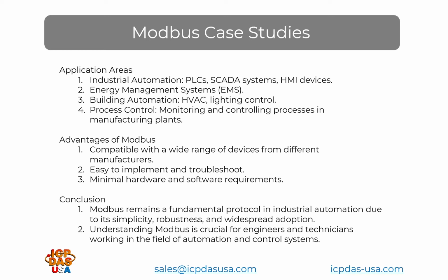Oh, I agree. But normally you want to look for the very first register. If the very first register starts at 30,000, then you know it's zero based. If it starts with 30,001, then you have a good chance that it's one based. If they skip zero, that's on them. That's a bad practice, and that's not how it should be used. But ideally, I just look for the very first register, and that usually gives me the clue, or it's usually in the documentation.